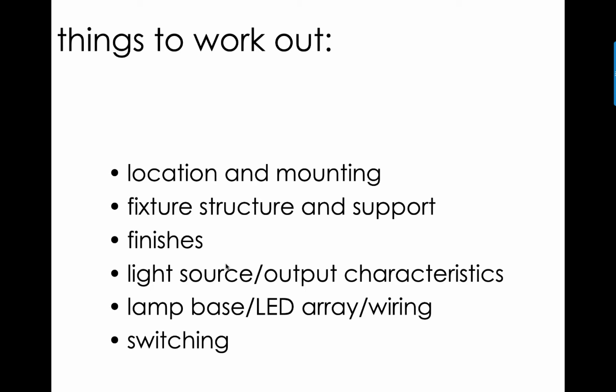Finally, the light source. Is it LED? Probably. But its output characteristics. Is it an uplight, a downlight? Remember, LEDs are particular in that they are directional. They only go one way. So if you have a recessed fixture, something custom where the LEDs are part of it, you'll have to think about that. Whereas if you have a screw-in lamp, a light bulb, you're going to need to provide some kind of socket, a base for it, and the wiring, and of course switching.